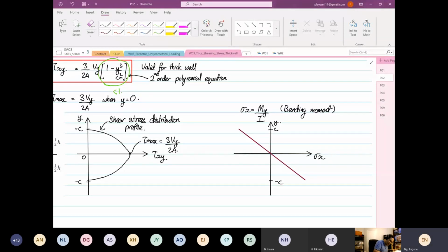So I will give you a hint. Oh, one you get negative and the other one you get positive? No, you're close. What do you realize? At the neutral axis, stress X is equal to what? 0. Yes or no? At the neutral axis, the shear stress is actually maximum. So over here you have 0, over here you have its maximum. So when you design your structure, what will you use? One is at a maximum shear, 0 normal stress, and the other one you have 0 shear, maximum normal stress. What will you use now?